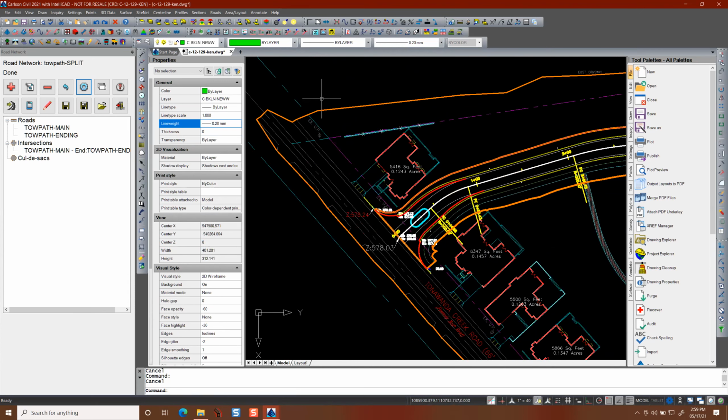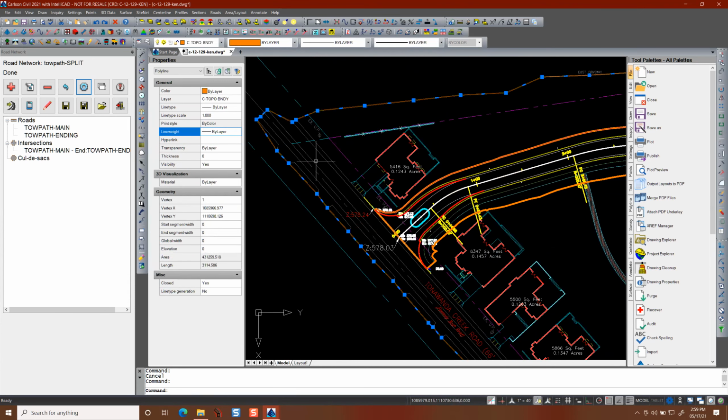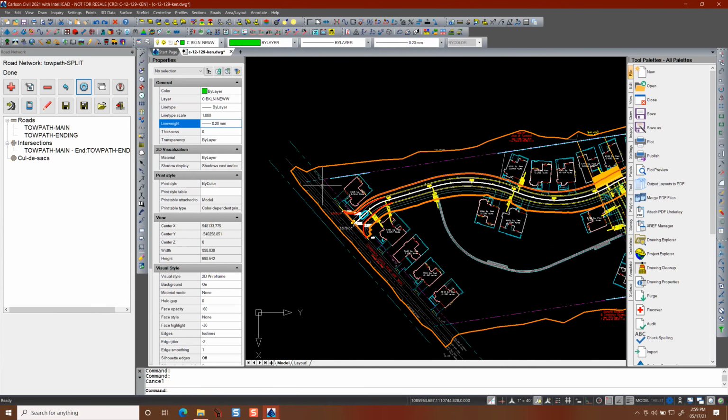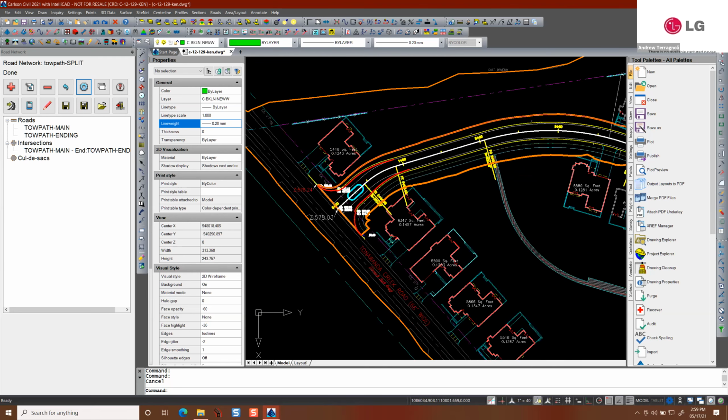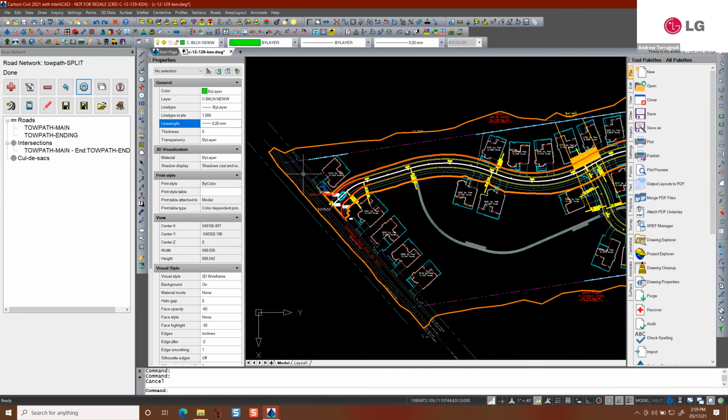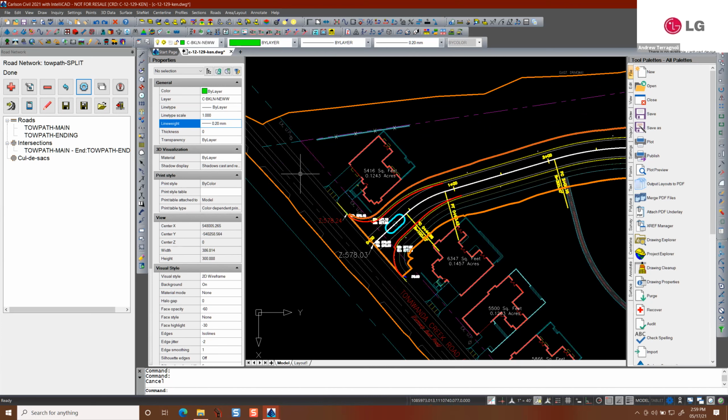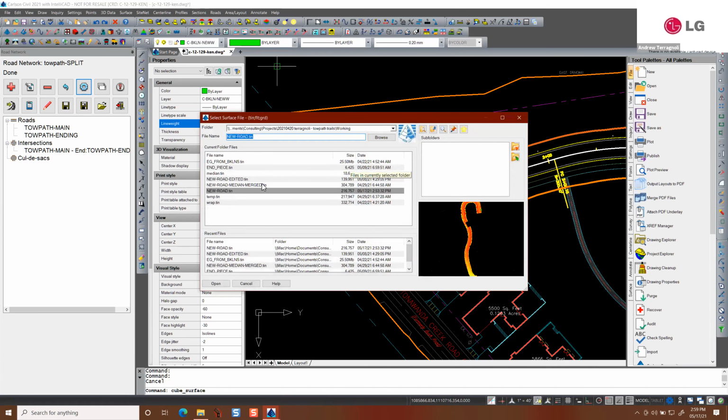In fact, there is the boundary of that tin file, but this stuff out here is really poorly defined. Yeah, I'd almost have to redo that road. I don't know what I would do. I would have to look at the spot elevations and make a new tin out of that road and use tin utilities to cut it.